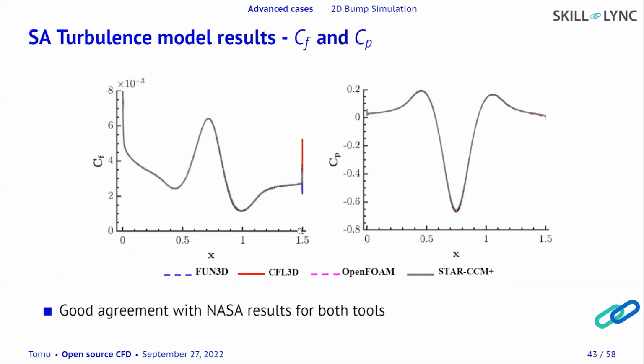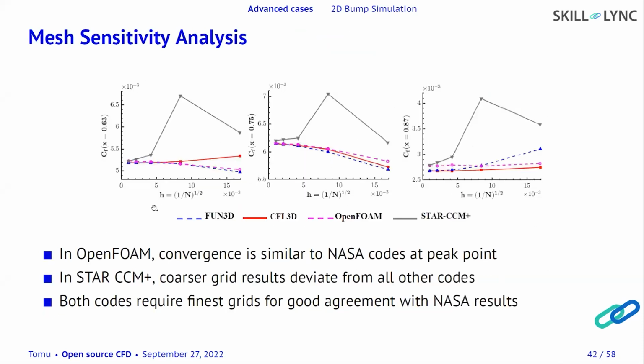So once they have conducted this grid sensitivity analysis, whatever mesh we are getting good results at, in this case it will be the finest mesh. So all the simulations that they want to run will be done on this finest mesh.